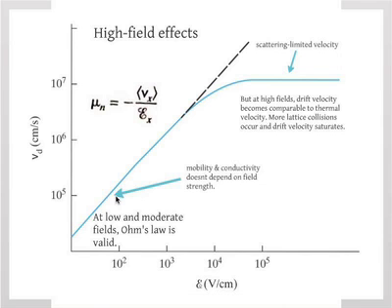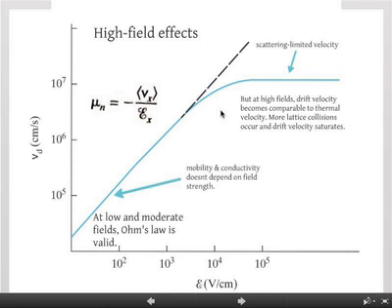Of course, it depends on the material. This is silicon. But this is, again, something you should be aware of. Okay, we'll come back to this later, so don't worry too much about it. So you can see if you get to about 10,000 volts per centimeter, then you have a problem. You have to worry about high field effects. Okay?